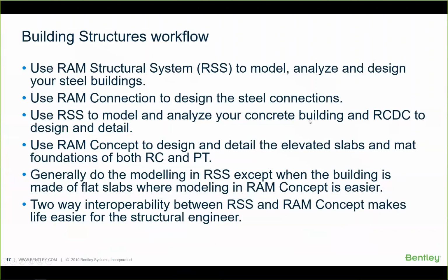If the building is a concrete building, then I suggest to use RAM structural system to model and analyze only in RAM structural system, and use RCDC, which is part of STAAD.Pro Advanced, which is again part of Structural Enterprise, to read the analysis results of the RAM structural system model, and then proceed with design and detailing of my concrete building components. Okay, so beam design, column, slab, foundations can be designed in RCDC.